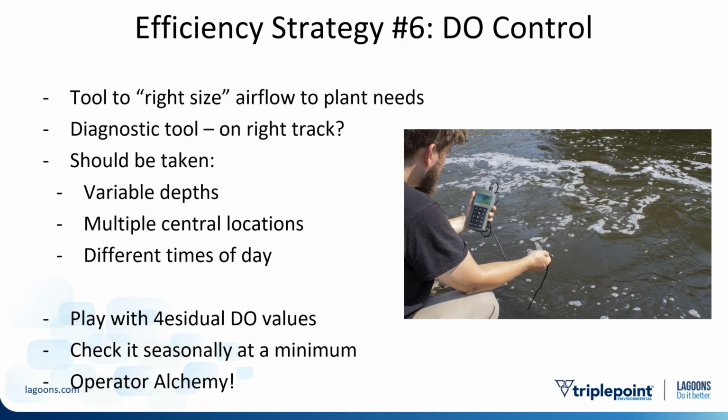And it's important also, if you're taking DO, to not just go over to the edge of the lagoon, flop it in, and take one measurement. It's important to take multiple measurements around the lagoon at multiple depths and also at different times of the day to get some representative idea of what the dissolved oxygen is in that pond.